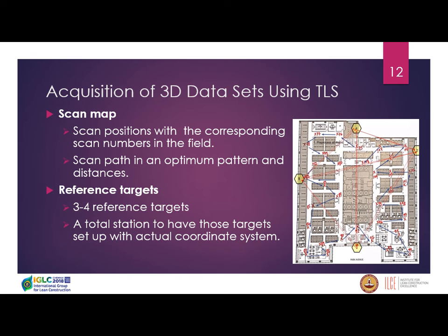And then we need to use totalization. Why? Because we need to get reference coordinates. We need to get a coordinate system, and we need to assign that coordinate system to those targets. It really helps us later, during the registration, to align those scans together.